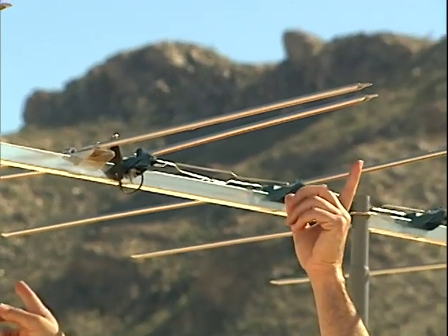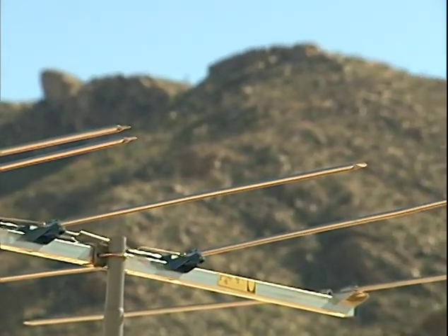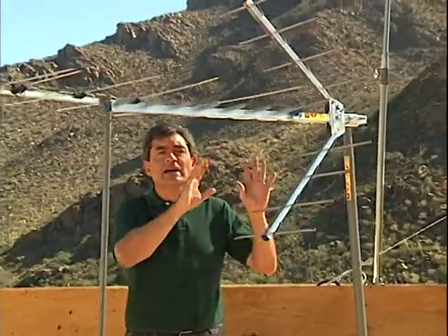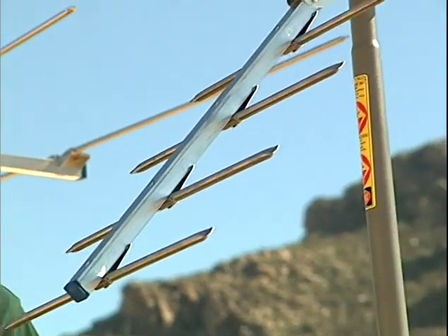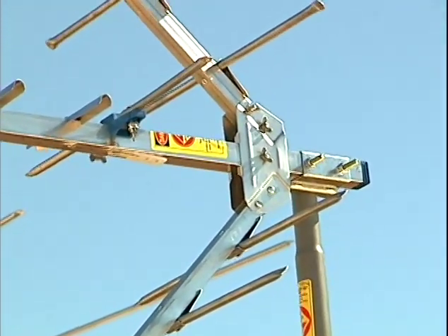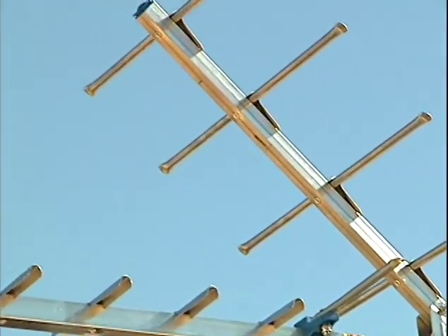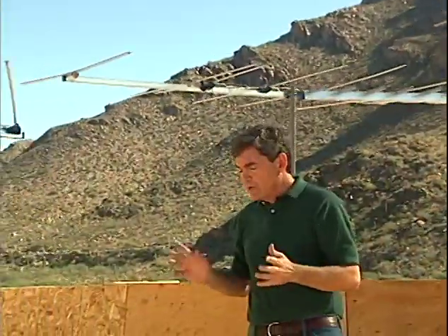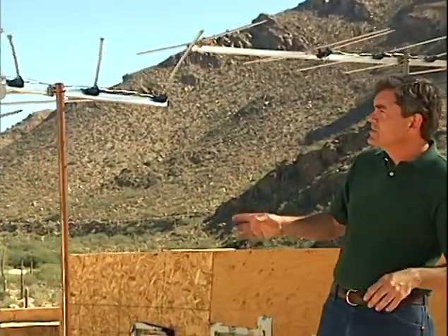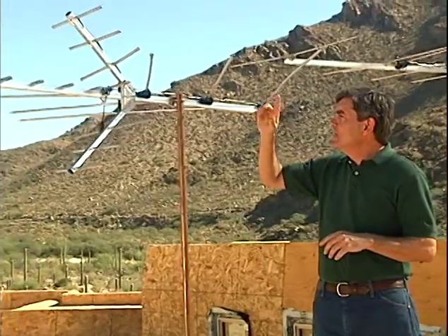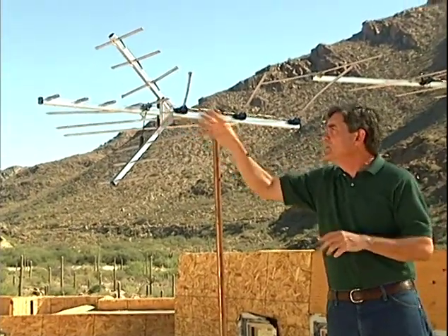They have longer elements due to the lower frequencies of those bands. This UHF-only antenna is designed to cover the broad spectrum of the UHF channels. It uses elements which are much smaller due to the very high frequencies of those bands. Now, some manufacturers combine the two into one design, such as this combination VHF and UHF antenna, which also covers